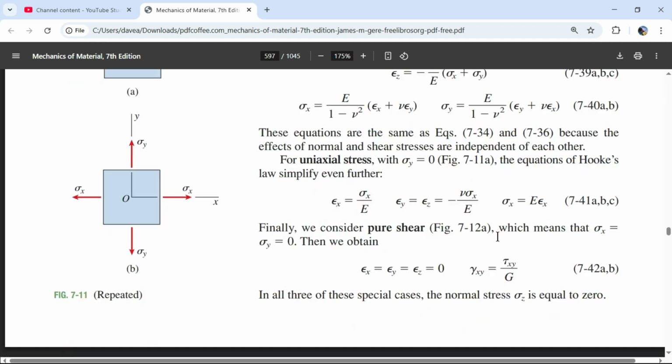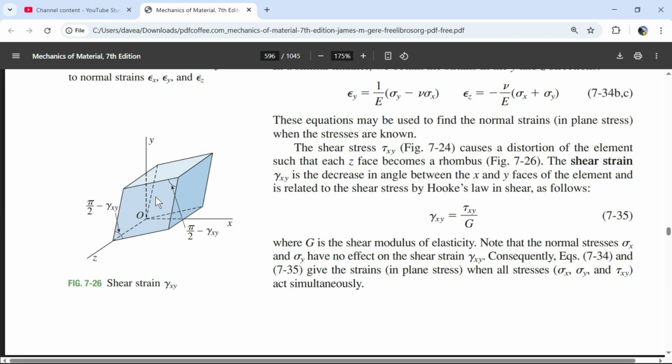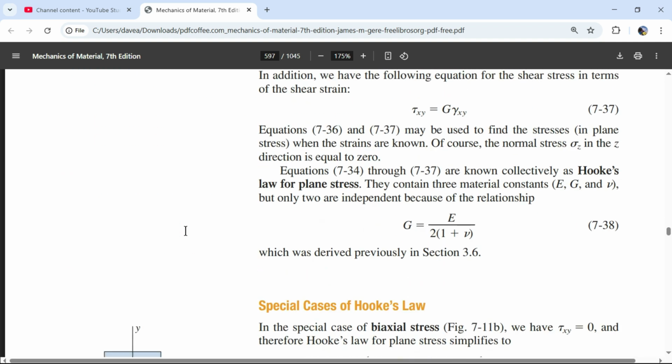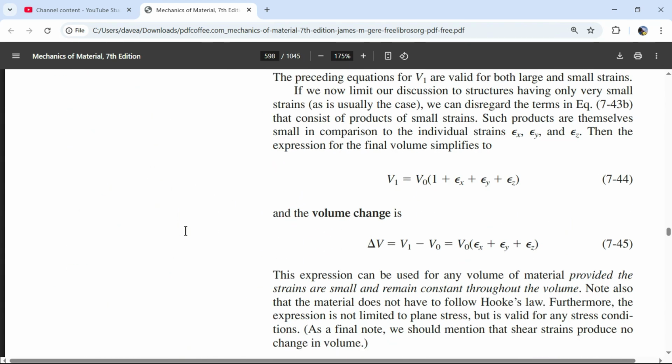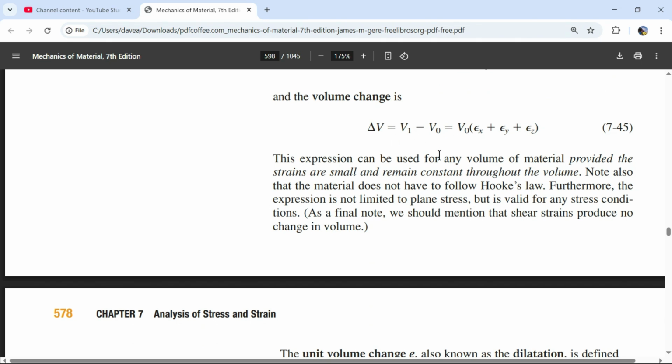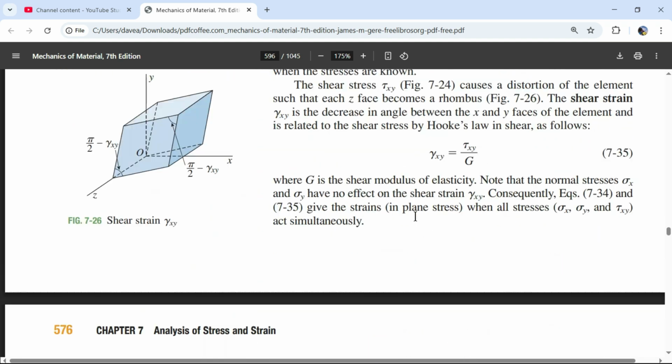Now, I've not gone over that one because it seems like, how is this volume the same as this shear gets to be large? This thing's just going to collapse in on itself and have zero volume. So with large shear strains, you are going to have a change in volume. So is it just the fact that this equation is based on small strains? I get that with small shear strains. If you hardly change these angles, I'm okay with there being no change in volume. But if you take it to the extreme and squash it in all the way, this length becomes 2 times as long, and then there is no more volume.